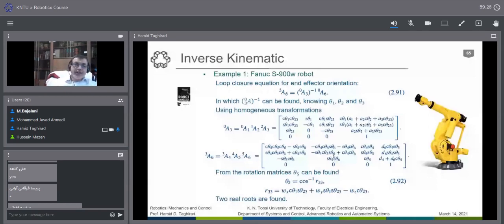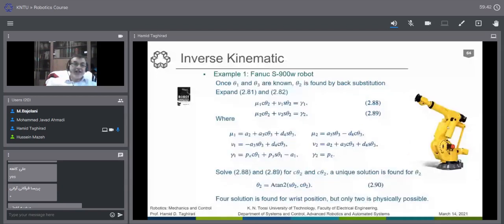The robot has some motion restriction. So suppose that if you plot the data, the 4 solutions for any cases, you can see that the angle of this joint cannot be minus 180 degrees. One of the solutions goes to that part of the problem, which is not practical.